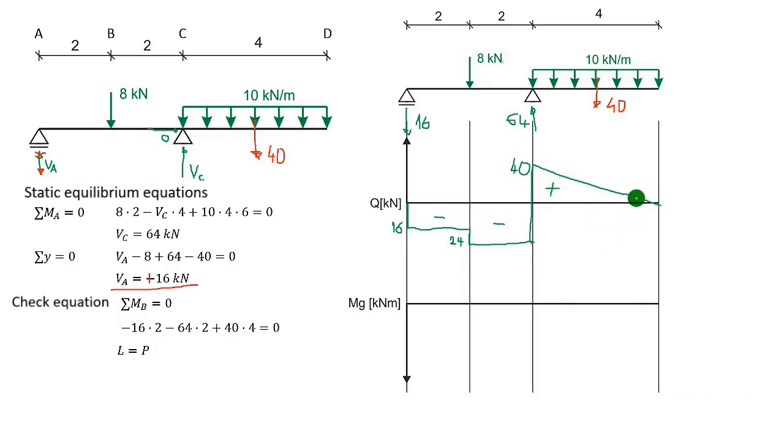And we can already draw one valuable piece of information from this shear force diagram. If under a continuous load on the shear force diagram the graph changes sign, then we would have an extremum on the moment diagram. And since under a continuous load the graph did not change sign, there will be no extremum here. So a little less counting.